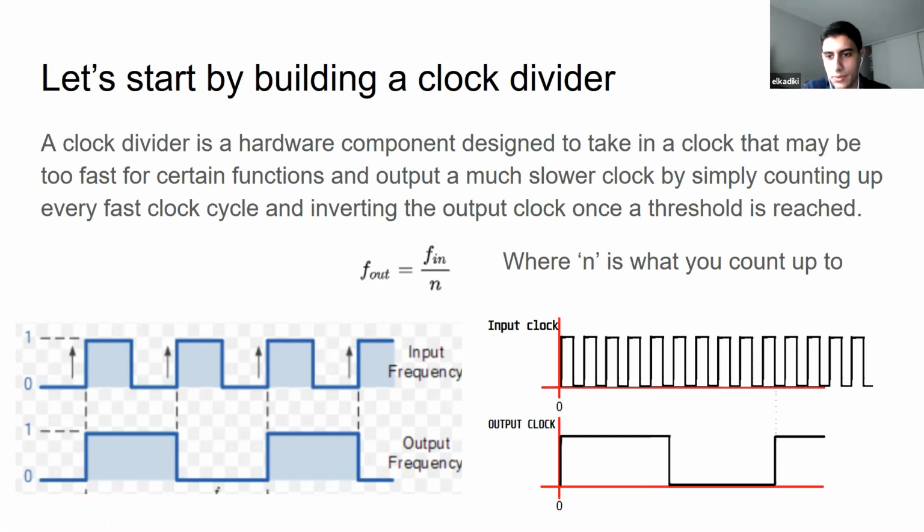So we actually want to shrink the clock speed a lot more. The whole idea of it is to just count. It's like one guy on the other side of the room is counting very quickly, and every time he hits 10, you count up 1. So after a certain number of input clock cycles have occurred, you'll have a transition in your output clock.